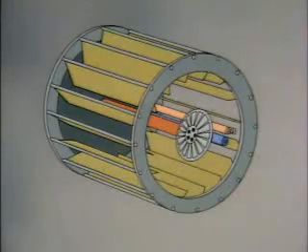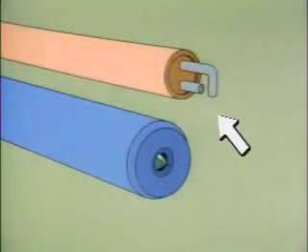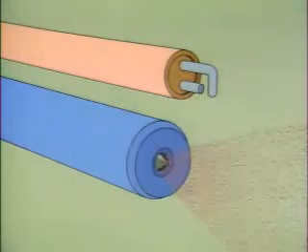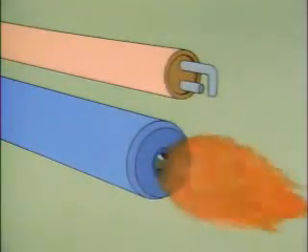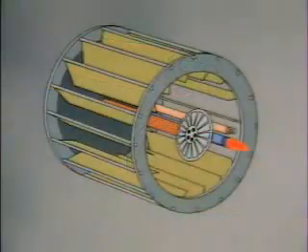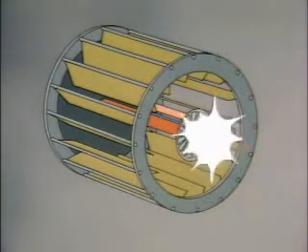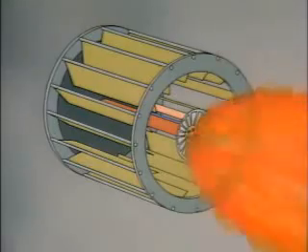To start the oil mist burning, there's an igniter. This igniter consists of a sparking device and a separate atomizer which serves as a pilot for the burner. A small amount of oil is sent to the igniter atomizer. The oil flows through a nozzle, which creates the mist. The spark ignites the oil mist. After a flame is established at the igniter, oil flow to the main atomizer is started, producing an oil mist. Then the igniter flame ignites the oil mist, and the combustion process begins.